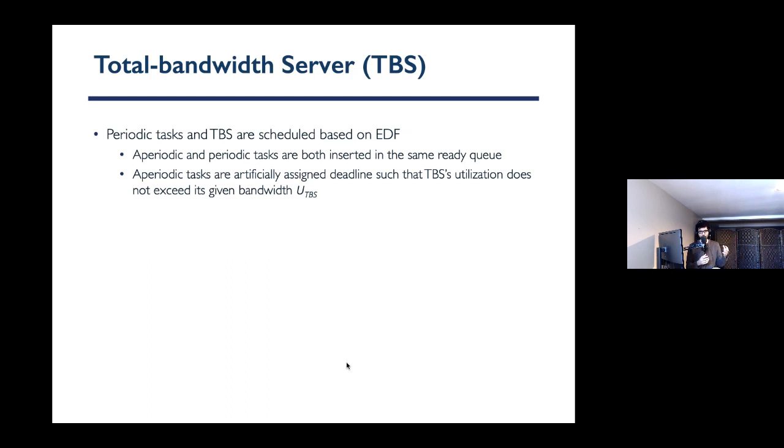So as long as you can make these new aperiodic tasks fit, because when you assign deadlines to your tasks, you're sort of defining utilization for them, right? It's a synthetic utilization because they're not going to come every time. It's going to be just a one-time thing, and they schedule and they go.